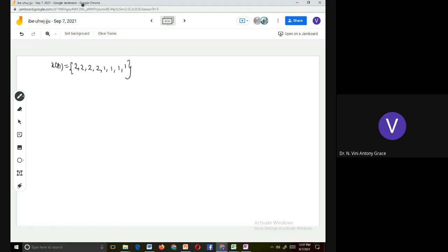During lab class, someone asked why for linear convolution we find the starting point, but for circular convolution we do not. The reason is, in linear convolution, the summation is from n equal to minus infinity to infinity, so it has infinite number of samples. But after finding linear convolution, you will get only finite samples based on the starting point